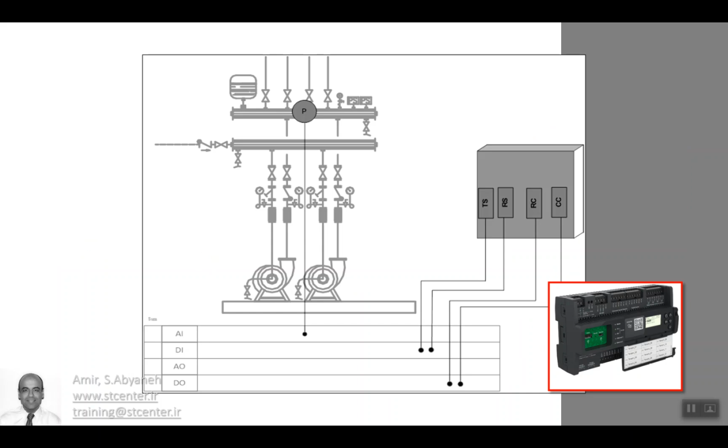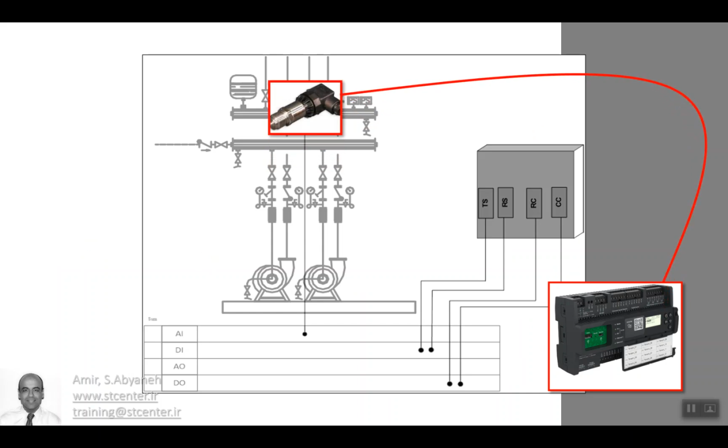In this picture, we are going to place the pressure transmitter at the right place. Also, we should make the wiring communication between the electrical panel and the compact controller. And that's it. So this is the case when you do not have Modbus or BACnet communication. In case you have it, it's direct communication between the booster pump and the control level in the BMS.